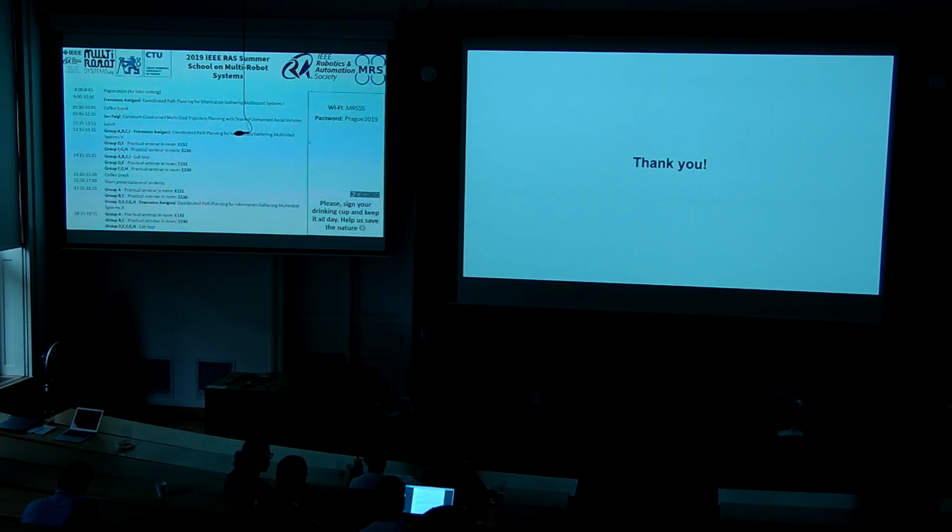One typical possibility is, for example, in frontier-based exploration, that I have a frontier, okay, and I try to put there the footprint of my sensor. Okay, and I look at how many unknown cells I can cover from there. Of course, this is an optimistic estimate, because I don't know if there is a wall just 1 meter beyond the frontier, but this is something that is usually employed.